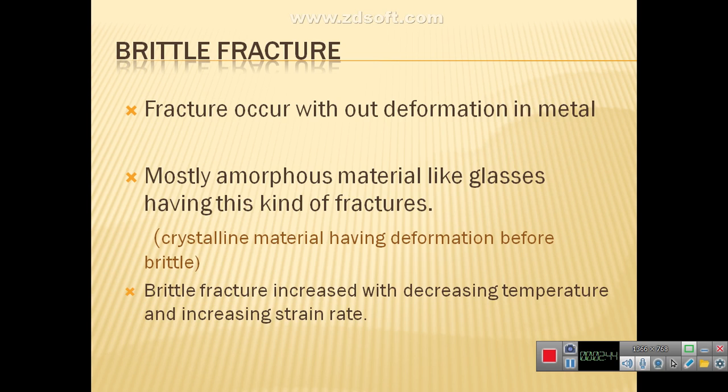Brittle fracture increases with a decrease in temperature and an increase in the strain rate of a material. In brittle fracture, no apparent plastic deformation is formed, and no crack formation or propagation is seen beforehand. In brittle materials, the cracks are very unstable.